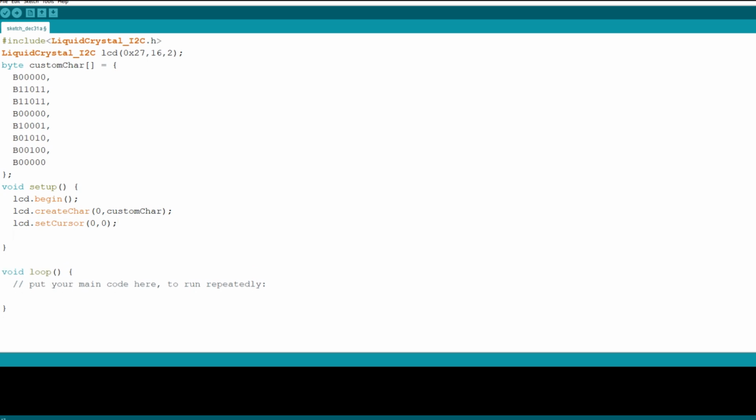We will learn a new function here too. Our function name is write function. With this function we can show the data in our ID number on our LCD screen. So let's write here lcd.write, open and close parentheses, and also put a semicolon, and let's move inside of our parentheses. We will define one parameter here. So the parameter will be the ID number. As you remember, our ID number is 0. So I will write here 0. If we do something like this, we get the result we want.